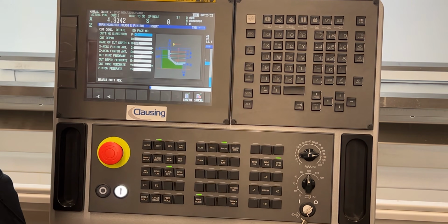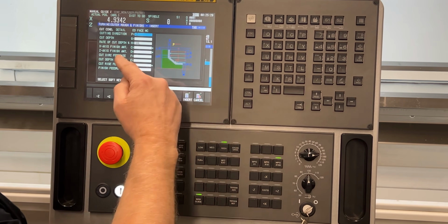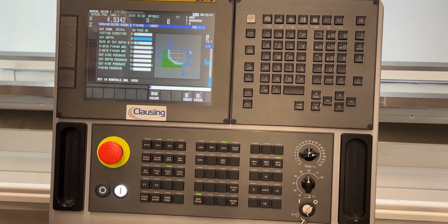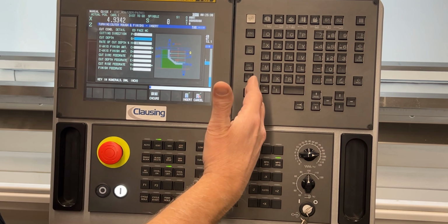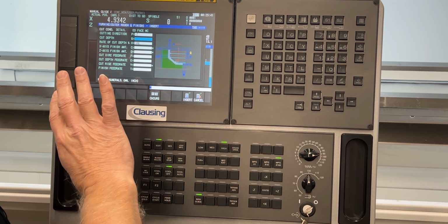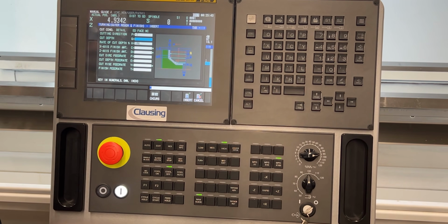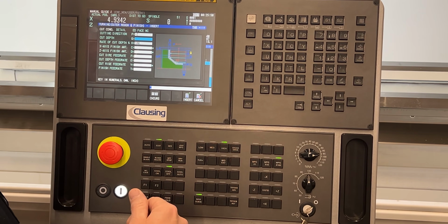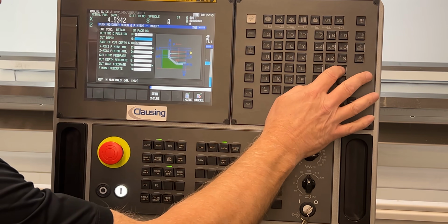And then the screen will come up for me to fill in the values of how it's going to be attacked. A Z minus motion is the first thing I'm going to select, because I'm telling it I'm going to be cutting toward the headstock and not a Z plus, where the direction is going to go toward the tailstock. I want Z minus on that. The cut depth is your single side pass, so I'm going to put that at 0.1 here.